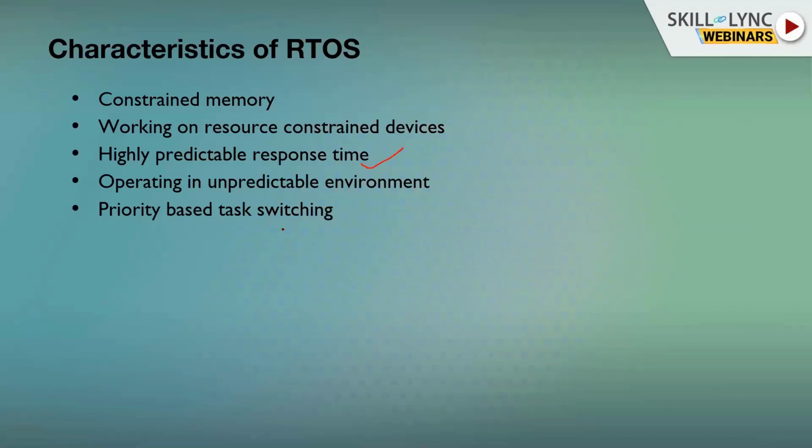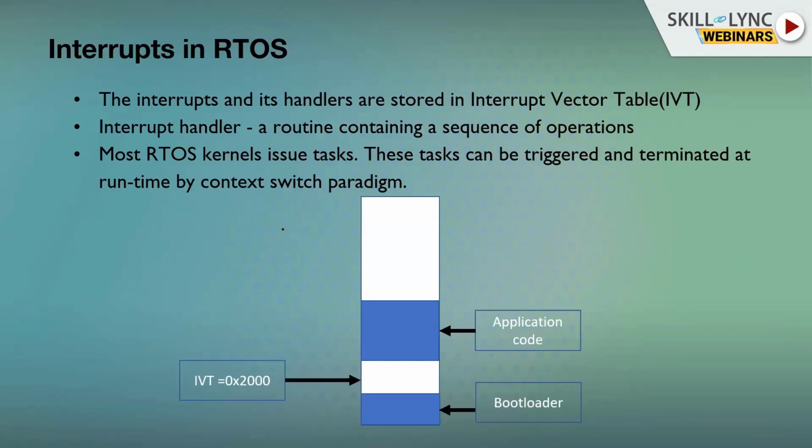And some other points that I can add here are that these real-time operating systems are going to be preemptible in nature. I did mention it as preemptive scheduling. Okay, it's a CPU scheduling technique that works by dividing the time slots of a CPU to a given process. There are various CPU scheduling techniques, right from round robin, priority based, shortest remaining time first algorithm, EDF, all those things. And then there is non-preemptive scheduling. Non-preemptive scheduling is also part of your general purpose operating system.